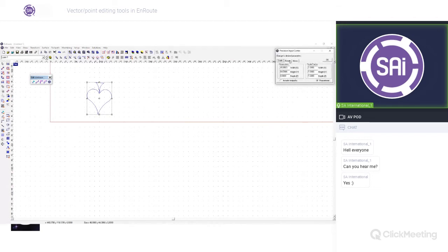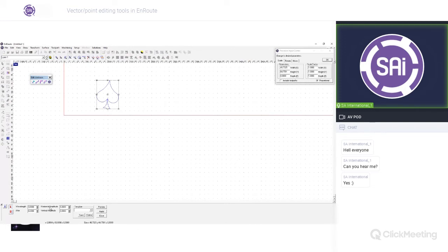So we'll just hit F2 to rotate it along the x-axis for 180 degrees, and then we'll just hit OK. Of course, as you can see, this one is pretty much a perfect contour. So what we can do is use the noise function to make it look like it was a badly vectorized bitmap.